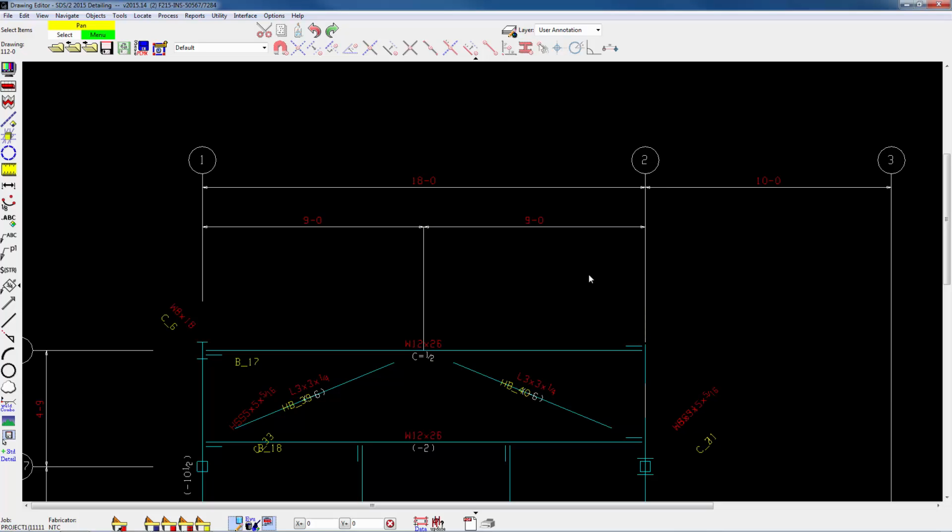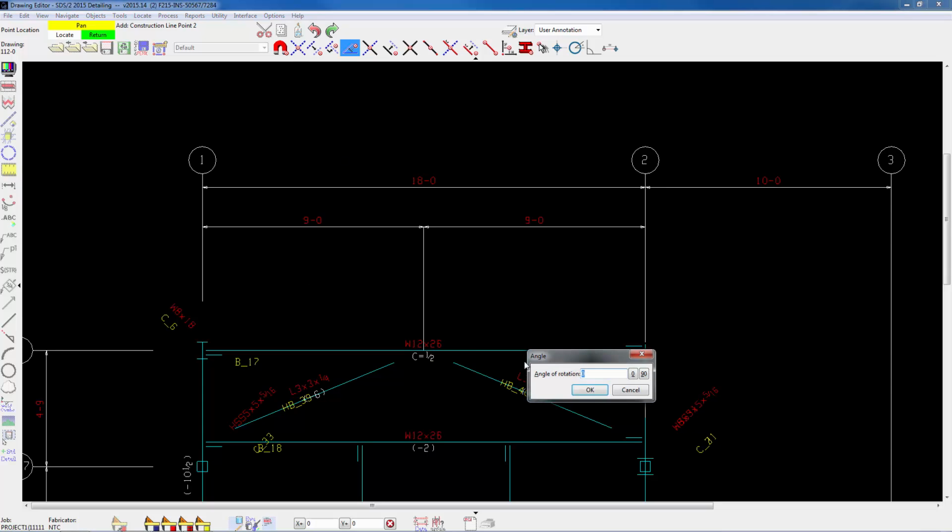The way I add in dimensions is to add in a bunch of construction lines. So I would go in construction line mode and pick add, and then using my auto point here, it'll select the center of the columns here, the exact point, the work point, and then for the angle, I'll pick angle and then locate and 0.